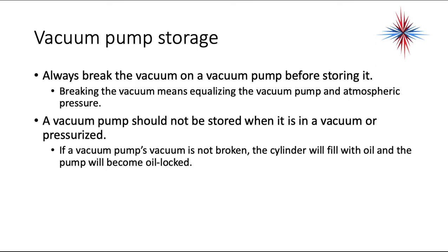Always break the vacuum on a vacuum pump before storing it. Breaking the vacuum means equalizing the vacuum pump and atmospheric pressure. A vacuum pump should not be stored when it's in a vacuum or pressurized. If a vacuum pump's vacuum is not broken, the cylinder will fill with oil and the pump will become oil locked.